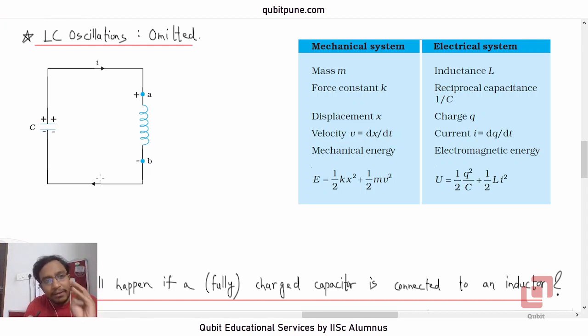That's it. What happens is the capacitor discharges, and its energy is stored in the form of magnetic potential energy in the inductor. Then the inductor loses its magnetic field, the capacitor charges in the other direction, and this continues forever, theoretically. What actually happens is the inductor wire as well as the connecting wires have non-zero resistance, so some energy will be dissipated there.